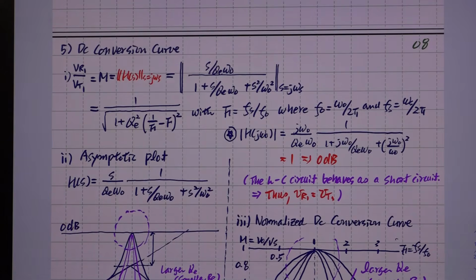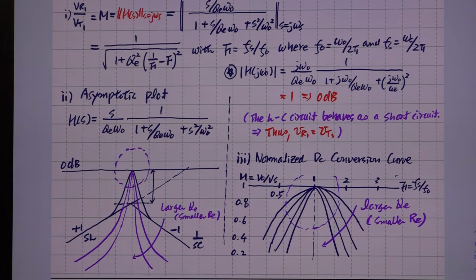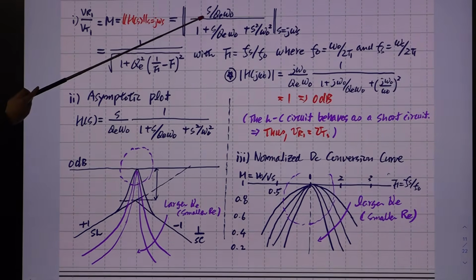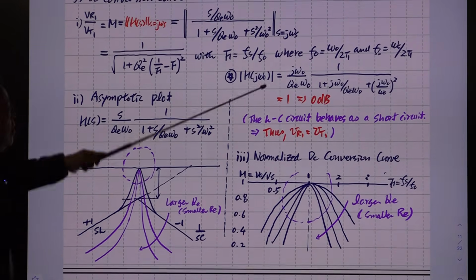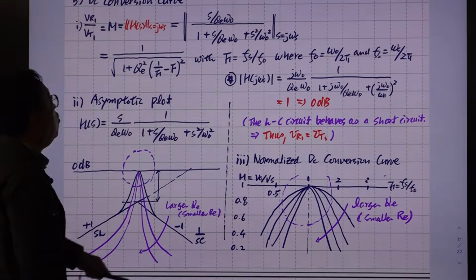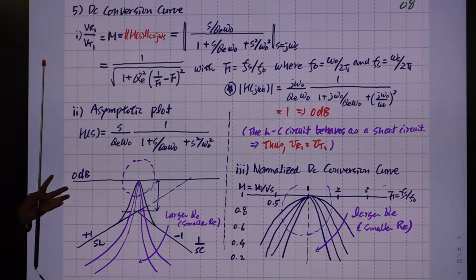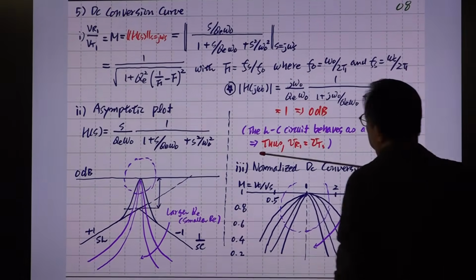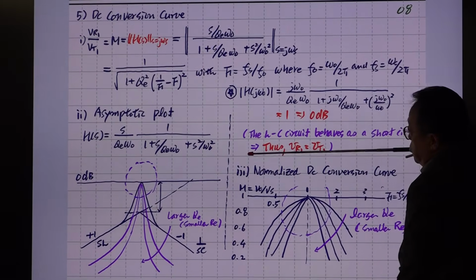So this is the repetition of the previous result, the final form. At the resonant frequency, you put j omega naught here and calculate. Then everything cancels and just 1 remains here. Or at the resonant frequency, the reactances of the 2 reactive components cancel. So you have simply a gain of 1 at the resonant frequency.